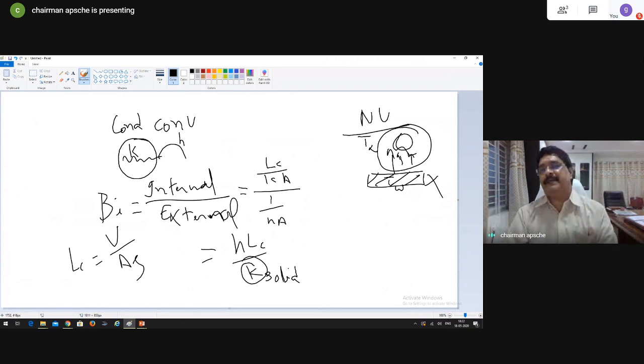When the fluid is participating in the heat transfer process, part of the heat is removed from the plate by convection because of the molecular movement, and part of the heat is taken away from the plate due to molecular interactions, or momentum exchange, with the molecules. Everything belongs to the fluid, and therefore the heat transfer is because of convection and conduction. Now, someone can ask you a question: okay, Q amount of heat is convected from a particular solid surface.